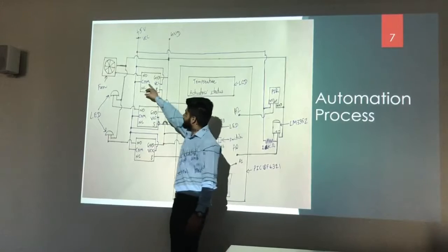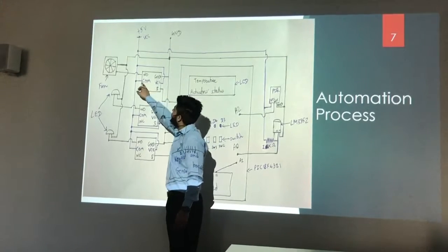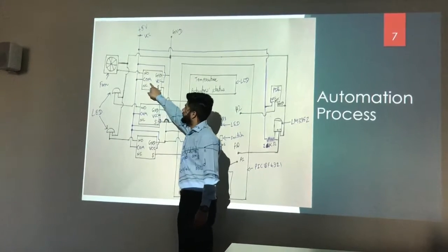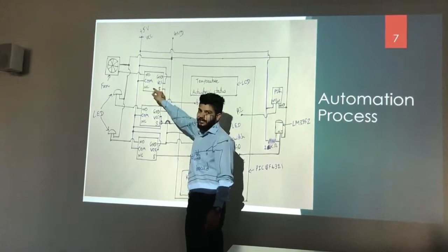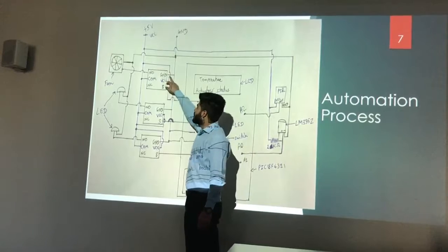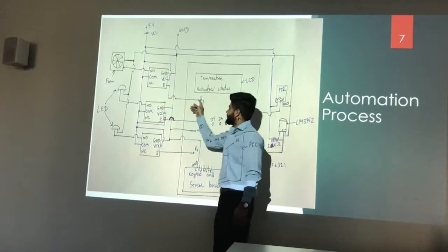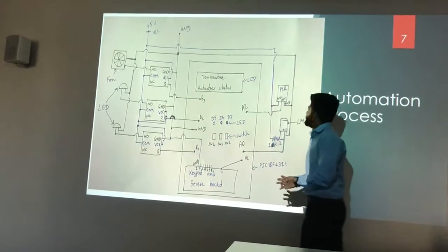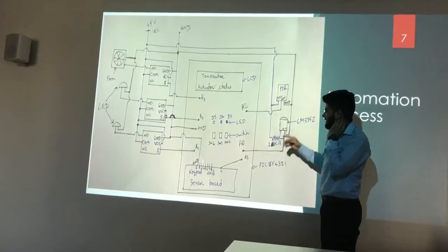And the plus VCC is also connected to the common of the relays, because I am giving plus 5 volts, and VCC is also connected to plus 5 volts. Ground is common, and the signal is connected to all the ports. I have written the program like that.